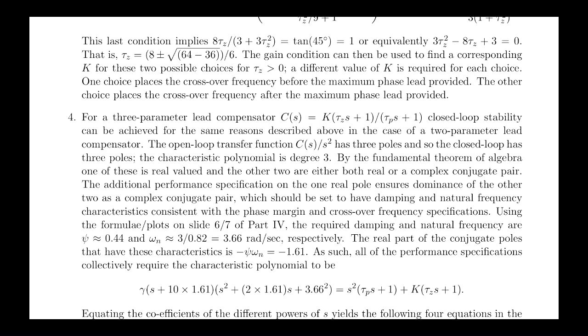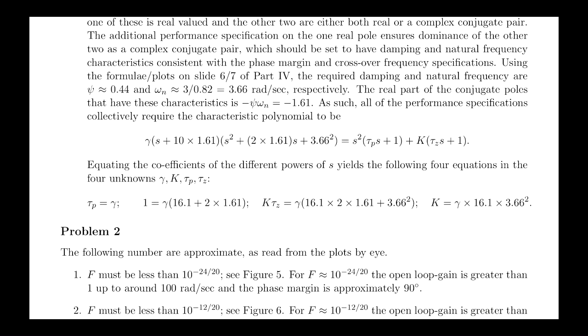And we've seen how in that situation, when that's a good approximation, we can translate our crossover frequency and phase margin specifications. Well, we've been going the other way, but you can go backwards, right, where you can take, on the basis of that assumption, your phase margin and crossover specifications back into a desired damping and natural frequency for your dominant second order dynamics, right? And if you do that, you get that you want this much damping and this much natural frequency. That will be consistent with the phase margin and the crossover frequency specification. I think these need to be updated.